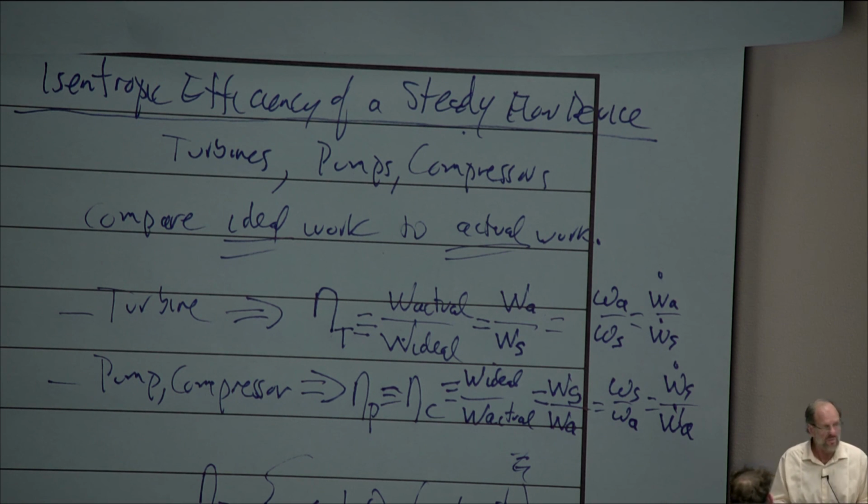I shall note that whenever you buy a pump, turbine, or compressor out in the commercial or industrial world, you're always given a curve that tells you exactly what the isentropic efficiency is for any known operating point for that particular piece of rotating equipment. So it's not like you're just going to be left hanging. Now, granted, if you go down to the Home Depot and buy some cheapo pump, turbine, compressor, whatever, they're not going to give you any information about that device. But if you're in the world of building steam power plants and you're buying a $200 million steam turbine, you want to know exactly how efficient that thing is. So that will always be given to you.